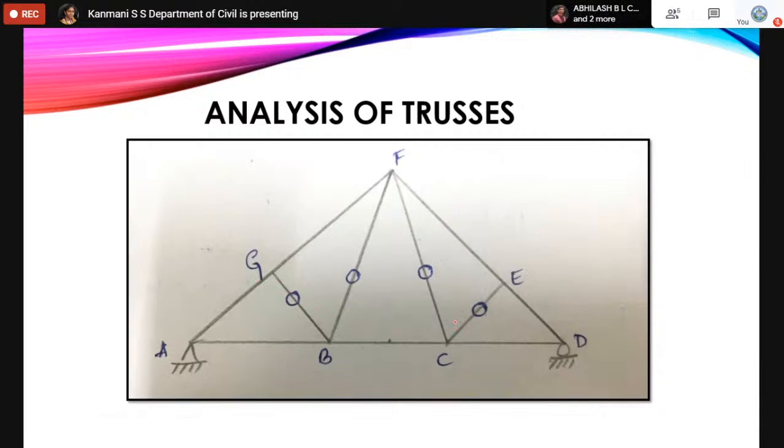See, these are member forces. Member forces are internal forces always. Once this load is applied, first it is tackled by the supports, then by the members. So these supports will also take the load of this entire truss. To resist this, there should be a certain amount of support reactions. If these reactions are found by equations of equilibrium alone, then it is a determinate structure. Degree of indeterminacy is 0.